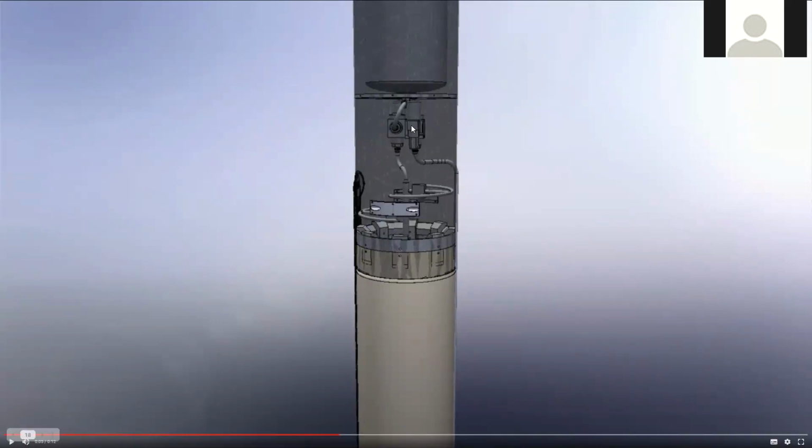So we use a form of pressure control called dynamic pressure regulation, which is basically an on-off control that regulates the pressure in the tank. So we have a very high pressure helium upstream, and we want to keep our tanks downstream at a certain pressure. And so what we do is we rapidly open and close these valves and then adjust the PWM.